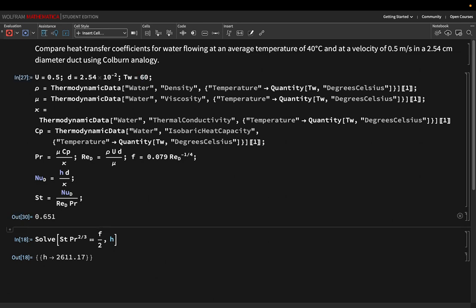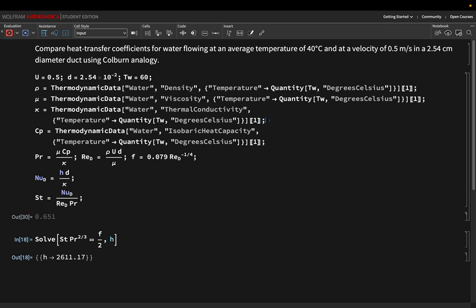So thermal conductivity is okay. For solids and liquids, it would be reversed. In case of solids, if the temperature has increased, the collisions will increase and that will reduce the overall thermal conductivity. However, in liquids, the higher the temperature, the more the movement, and the thermal conductivity actually increases. So this is increased and this is reduced.